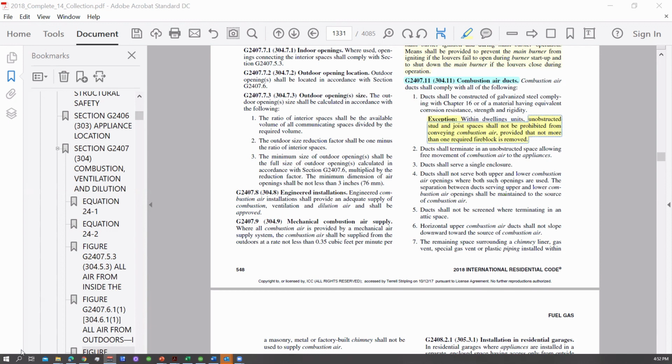Yeah, it's called depletion of combustion air. It's called makeup air. That's that house that I showed you, remember? We call it makeup air. You have to bring in enough makeup air for any type of exhaust or exfiltration. So go in the index of the code book and you look up makeup air, you will find your answer in that code section. That's exactly what you're talking about.